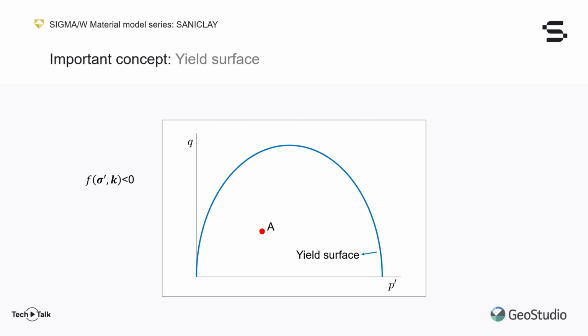Here is a yield surface visually represented in 2D on a stress plot. Keep in mind the yield surface is generally a 3D equation, since stresses will develop in every direction for complex loadings. Any stress point such as A, located inside the yield surface, will only produce elastic strains once loaded. A point located exactly on the yield surface, such as B, will produce elastic-plastic response when loaded. Finally, a point located outside the yield surface, such as C, is inadmissible since it supposes the stress point currently exists beyond the resistance available.